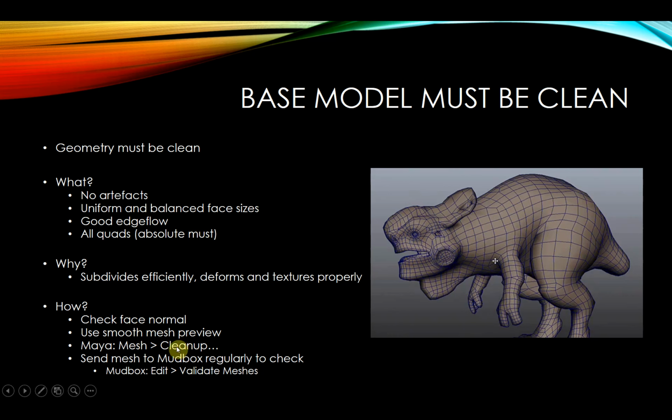Press 3 to see the smooth mesh preview in Maya to really check that it's working. If there's any artifacts in that, they need to be cleaned up. Make sure that your faces are kind of even across the model.